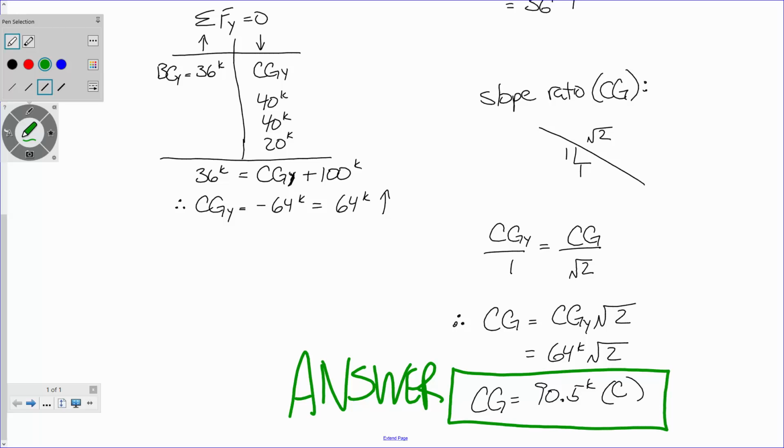So why would we do it? Why would we want to do it to the arbitrary point to the right of? Well, you could, let me say this. If you're comfortable with all the dimensions and the slope ratios, do it. I wanted to sum moments at G because every time I've ever encountered students who've done this stuff and I never taught them, they usually feel comfortable with those common points. So it's like, let's just sum moments where it feels natural.